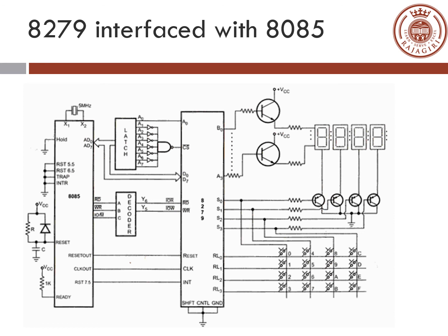Then we have the 4 scan lines coming out, and in this case they are directly connected to the matrix keyboard and the LED display, because we have only a 4x4 matrix and 4 LEDs in this configuration. So we don't need an external decoder to generate 16 lines. So that shows this connection.